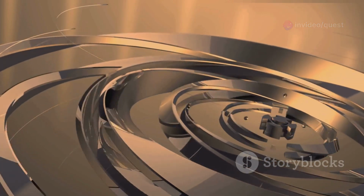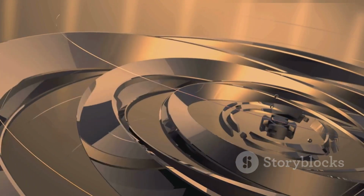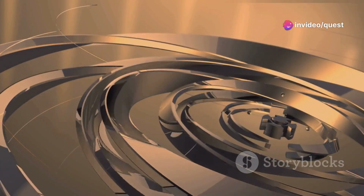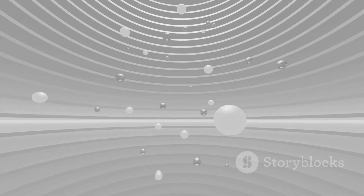This line will form an angle with the horizontal axis. Here's where the magic happens. We're going to rotate this line by twice its original angle. Why twice? Well, it's because in Mohr's circle, angles are always doubled. This is a crucial point to remember. Following the rotation, we'll find a new point. This new point represents a different stress state, but on the same plane within the material.